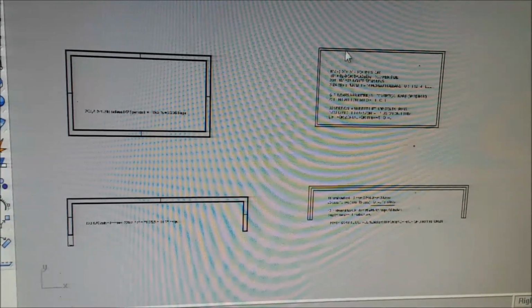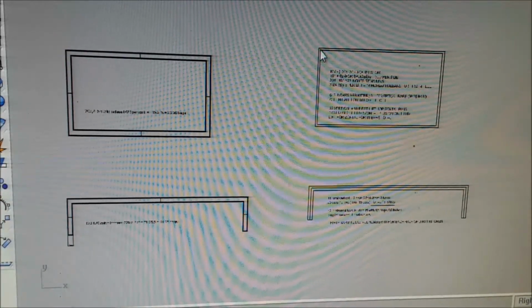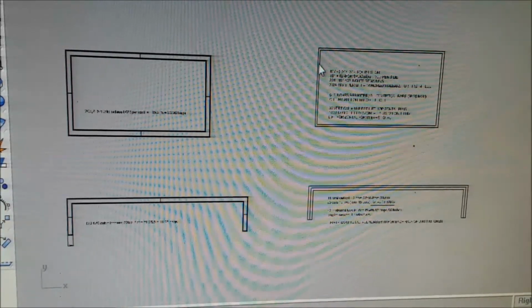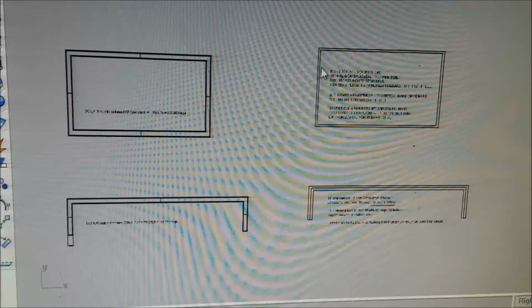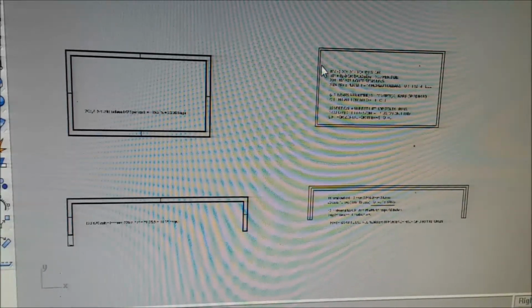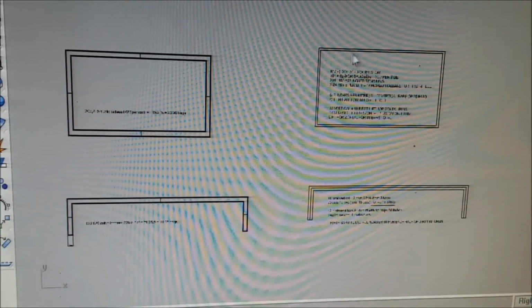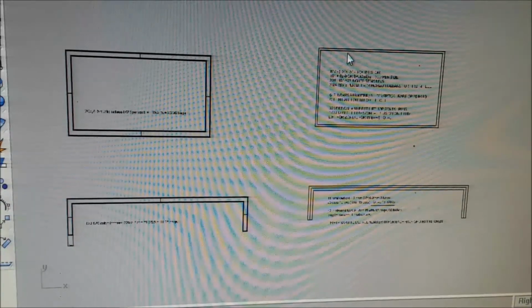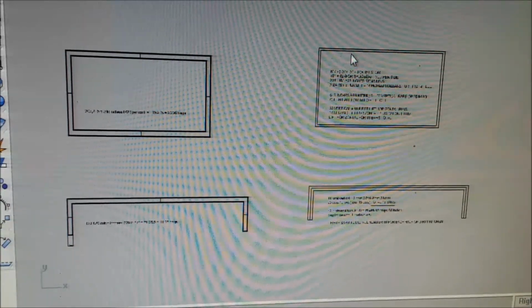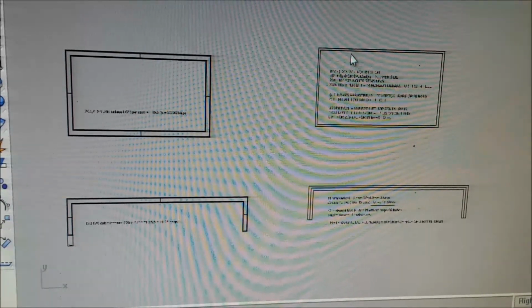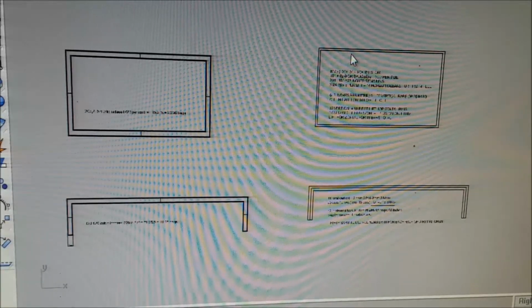It's all 1 monolithic pour of concrete, and a lot of those have a bigger diameter bar in the corners, and on the bottom of the beam will have a bigger bar where it's in tension. And the amount of steel in the wall is just a wash.